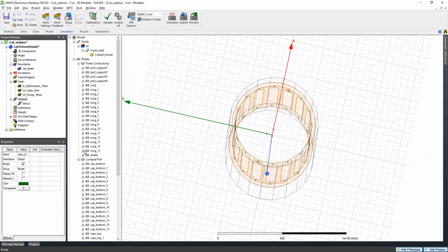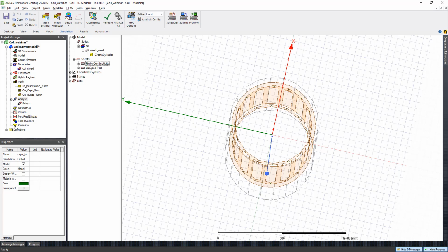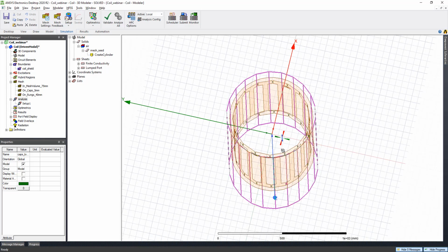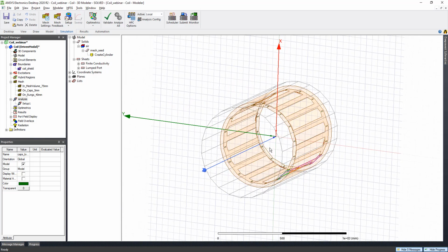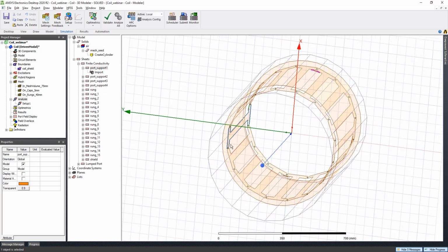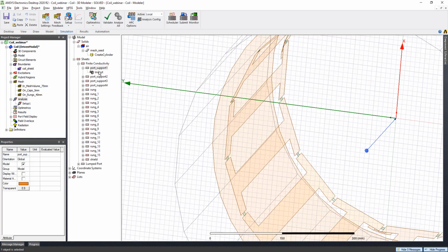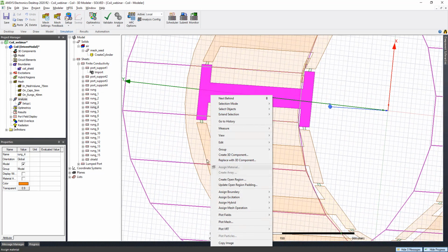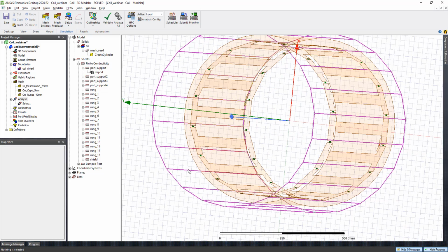The next thing is we need to set up the material properties and the excitation ports. I'm making everything simple here, so we are using sheets. This is a 2D object with no thickness in this case. But if you import your object, you are always welcome to assign a material to it. In this case we don't have it.